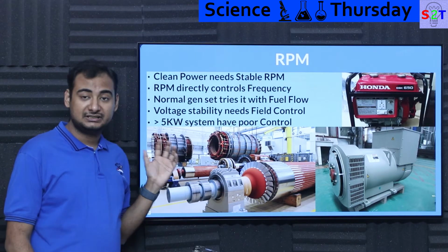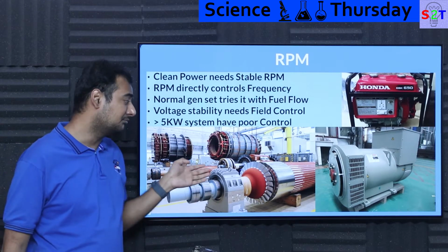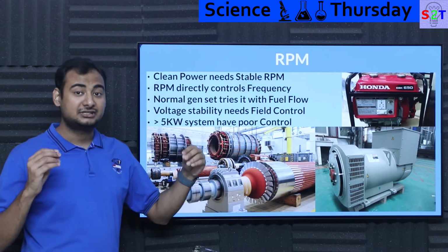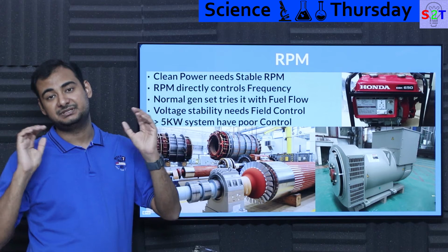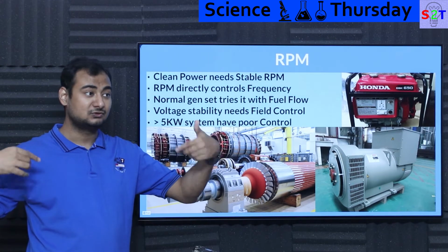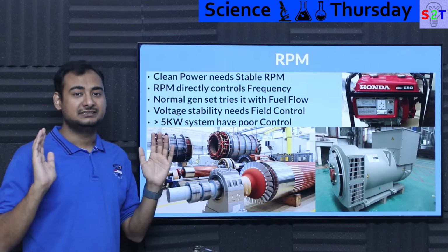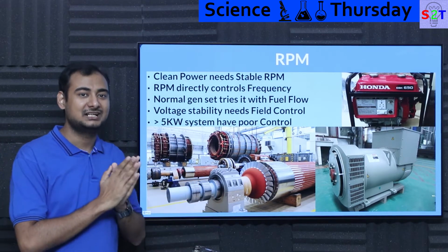So at this point in time, you can literally go to power plants, even if they have small generators that are 100 megawatt, they will have multi-ton rotors connected to multi-ton turbines, and sometimes the total rotating spinning mass could be as high as 600 ton or even higher. The benefit of that is there is no force in this universe that will stop that instantaneously.